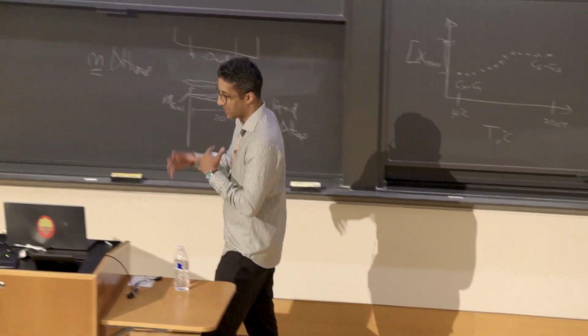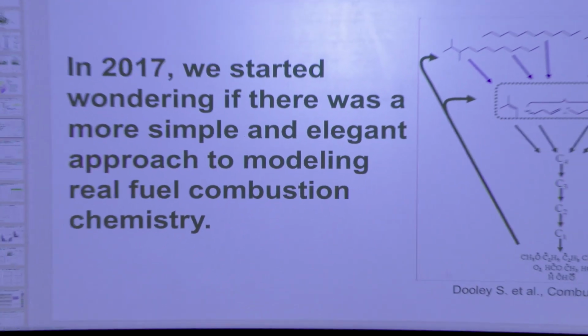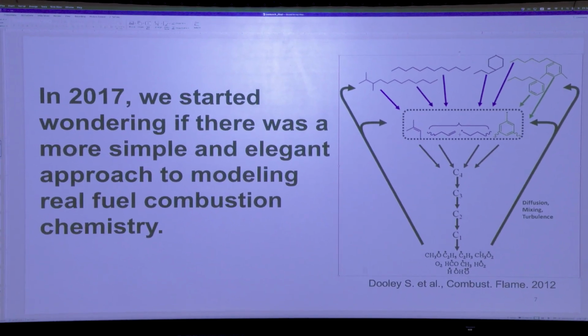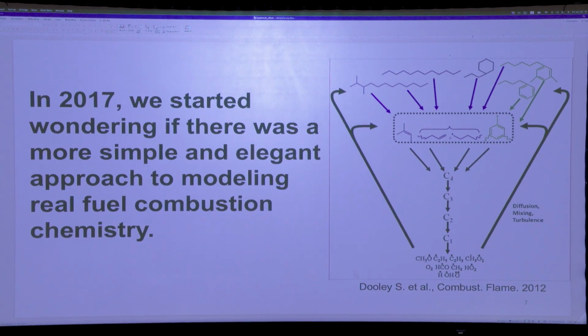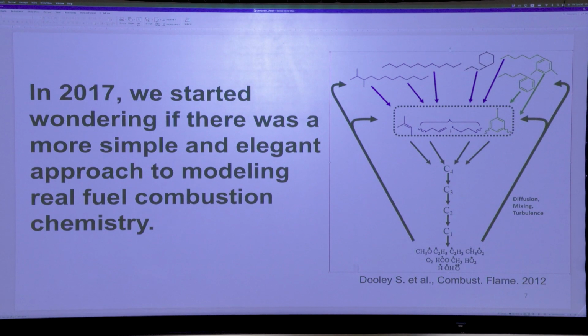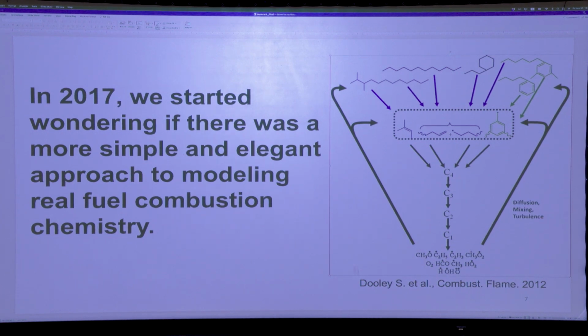So yeah, we were talking about how real fuels, even though they're complex mixtures, and every mixture can be quite different from the other, somehow when they start burning, the kinetics approximates overall features that are similar, provided some of their key initial physical chemical properties like density, viscosity, distillation curve, RON and MON or cetane number are similar. And we start to then try to understand a bit more what is really governing the combustion of complex mixtures.